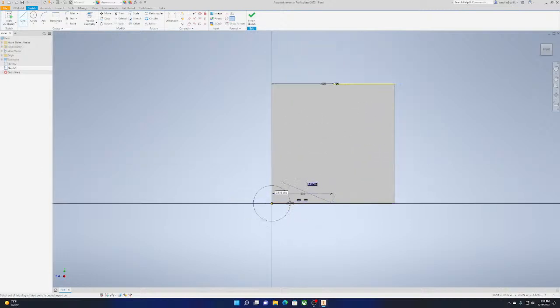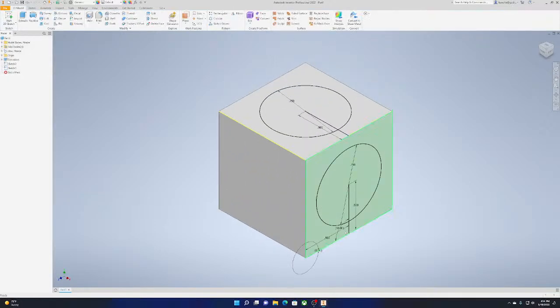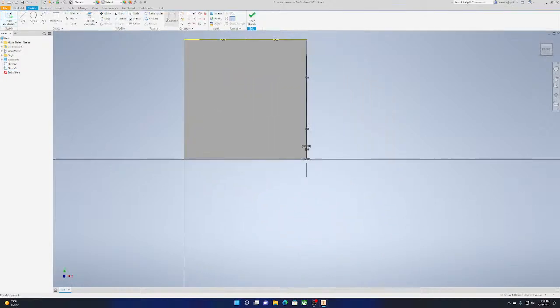This is just showing 0. That's circled. That's not just a dimension line. And then right here, say I'm off the wrong angle, I can do 0.5, and then I can do 90 and it goes right there. And then 0.75. Cool, finish sketch. And you can see I've made 2 sketches already on here. And I'll make my 3rd sketch. You also snap to your 0 degrees if you're near it, and your 90 if you're near it.